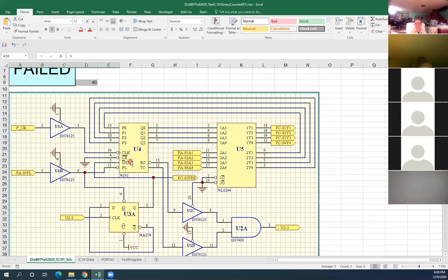Unless it didn't get the right logic out of U3. No, U3 you already verified on that, the preset. You already made sure they get a 1 already. Is something wrong with U3 pin number 5? Okay, 50-50. I'm staying with number 4.